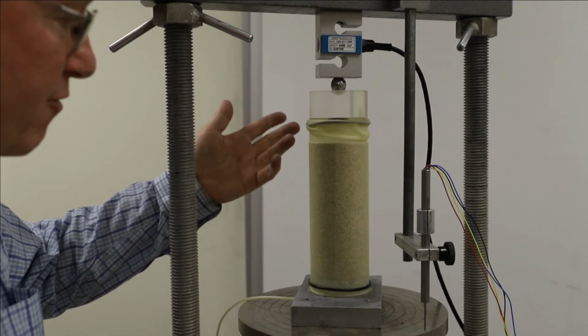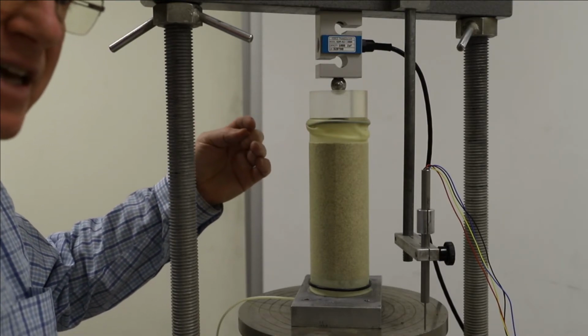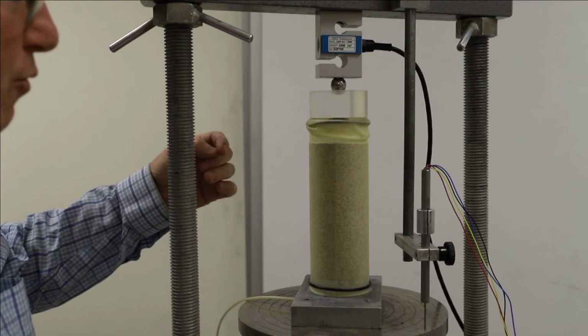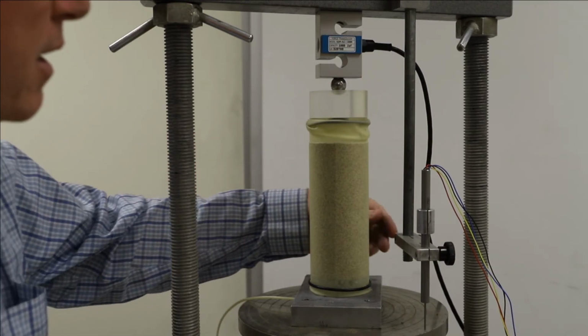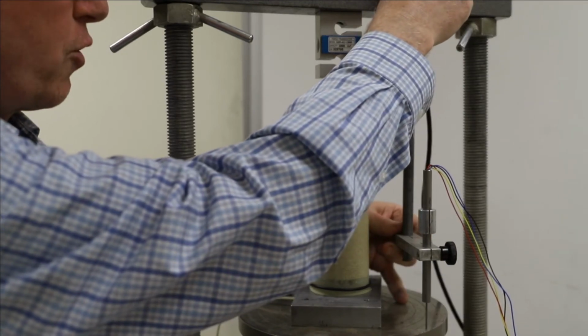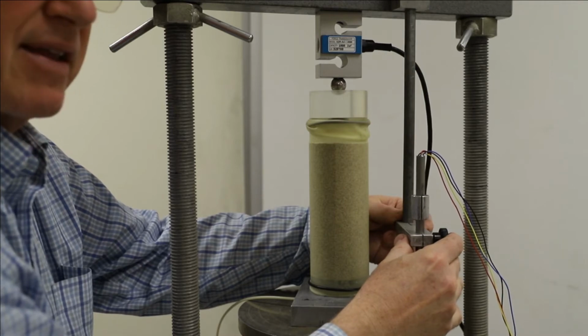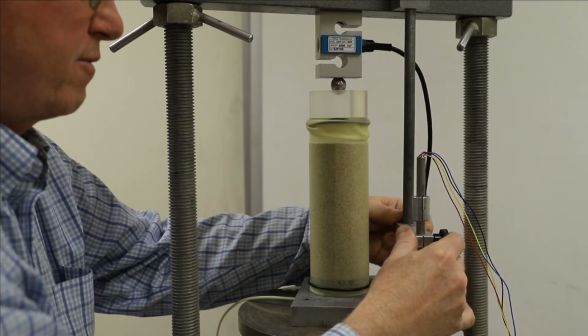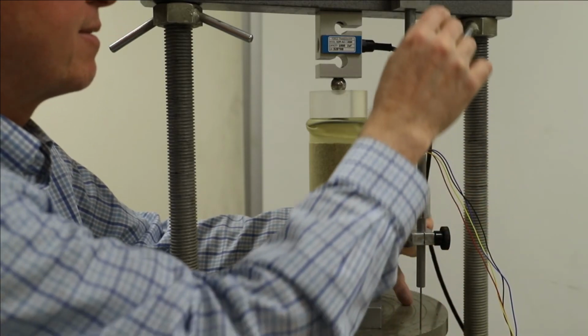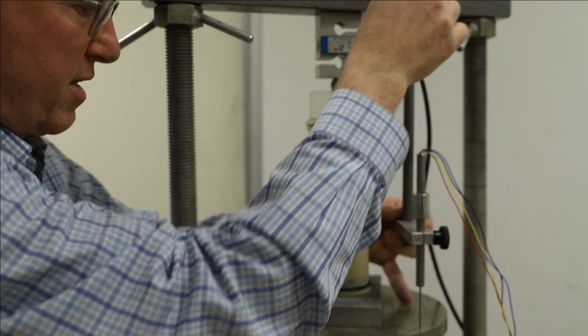And certainly the rotation isn't something we want to see, but at least if there's that tendency, then we see that it's happening, whereas we wouldn't know otherwise. The LVDT is in place, but it's not at a good value. We want to leave plenty of range for it to move and be recorded.